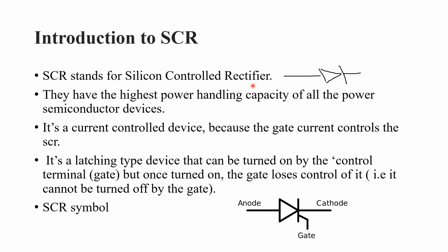On the other hand, silicon controlled rectifier belongs to the thyristor family, and as discussed earlier, it has four layers, PNPN, of P and N type material. And the thyristor family is used for high power application. So SCR can withstand high voltage and hence it is used for high power application.